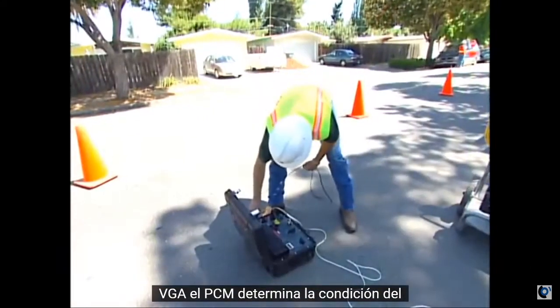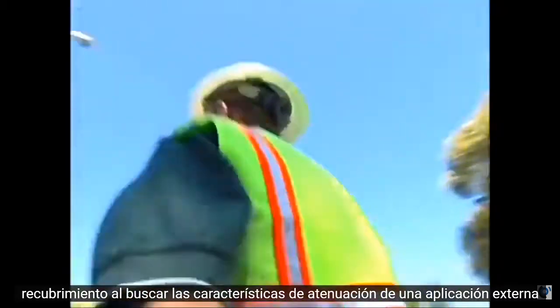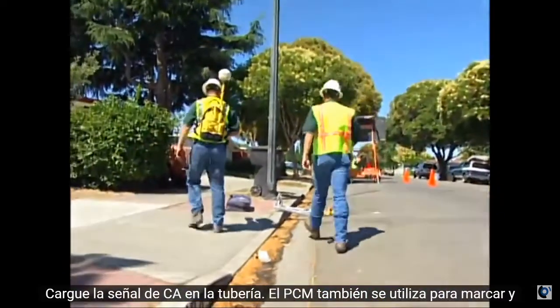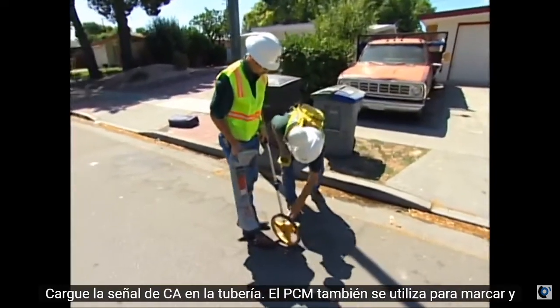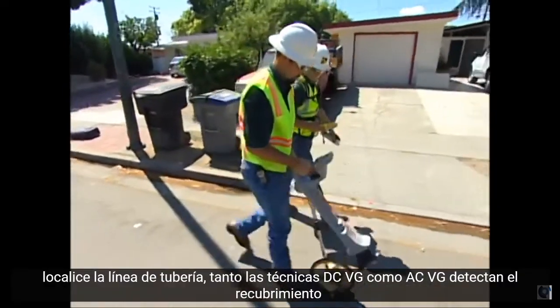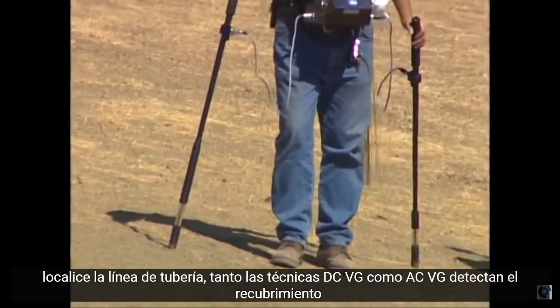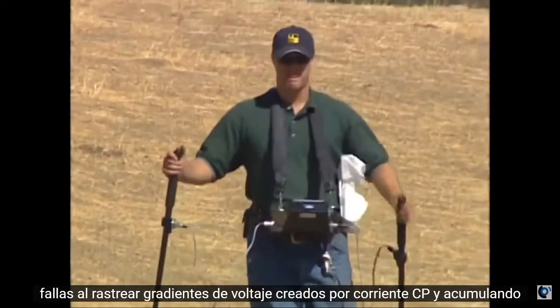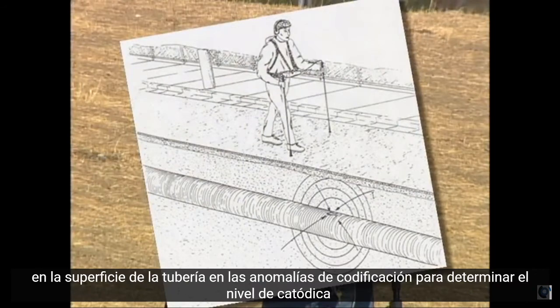The PCM determines the condition of the coating by looking for attenuation characteristics of an externally applied low-voltage AC signal on the pipeline. The PCM is also used to accurately mark and locate the pipeline. Both the DCVG and the ACVG techniques detect coating faults by tracking voltage gradients created by CP current and accumulating at the pipe surface at coating anomalies.